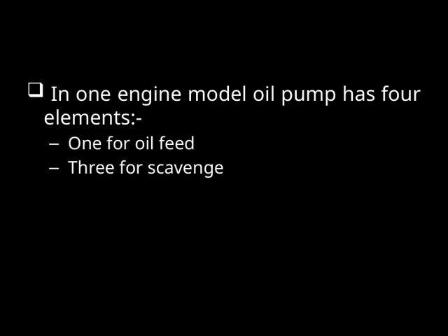Then, we have three elements focused on scavenge. These work together to remove the oil after it has done its job of lubricating the engine parts. The scavenging process is crucial because it helps maintain the proper oil level and prevents excess oil from accumulating in the engine, which could cause issues like increased pressure or overheating.